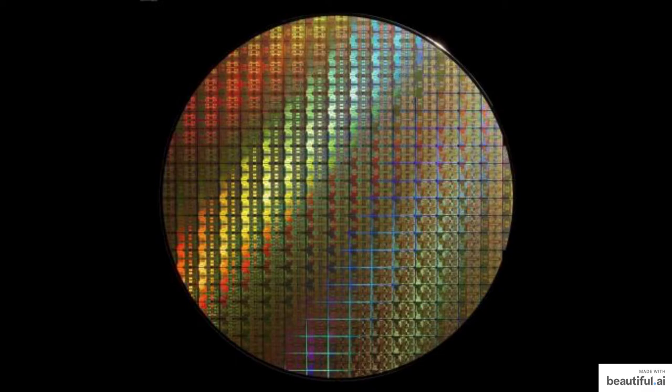So other reasons why silicon is chosen, well, it's really cheap, it's the second most abundant element on Earth after oxygen, and it's very easy to manufacture. Silica sand, silicon dioxide, can be melted into a cylinder, and that forms a pure silicon ingot, which can then be sliced to about 0.5 millimeter thick. These slices are called silicon wafers, and like the one above, they're then cut down into individual square chips, ready to be placed on your phone or computer.